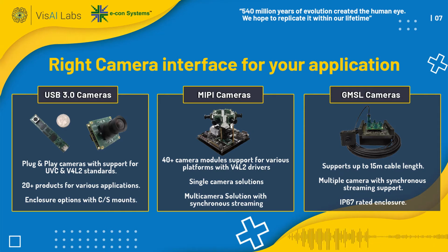These are UVC cameras. You can connect them to a PC, and they can use the default driver, whether it is Windows or Linux. You don't need any additional driver for these UVC cameras. That will give you an idea about what kind of image quality you are getting with this camera. If you want to continue with USB, you can. And if you want to switch to a MIPI or GMSL camera, then it is possible, as all our USB cameras are also available in MIPI and GMSL interfaces.